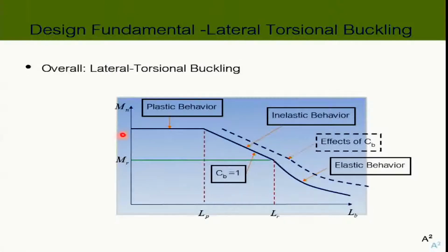Okay? And this, ladies and gentlemen, this curve is based on the pure moment case, meaning you will have this line when the bending moment diagram is constant. And when you don't have a constant bending moment diagram, it means that you can raise this line by multiplying it with Cb.